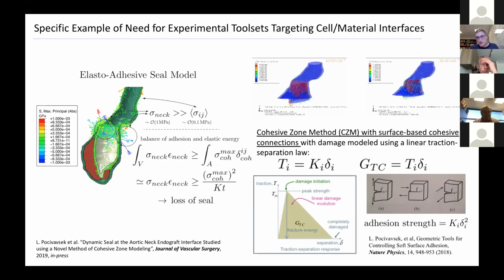So often we can model this from the standpoint of an adhesion energy, which is very common to do in physics. However, the specific stresses of those interfaces matter as well. And this is something that's well understood within fracture mechanics, more at the engineering side actually than the physics side, that the particular stress or peak stress that the interface can carry sometimes dominates how a crack will propagate through the surface independent of the fracture energy. And for other surfaces, fracture energy actually dominates, and the particular peak stress does not matter.